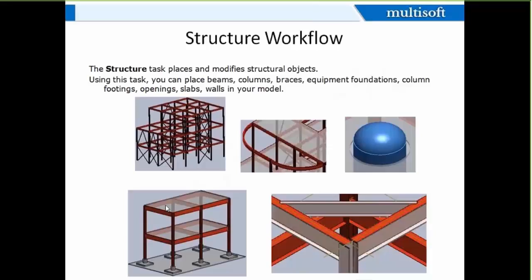You can see here there are different types of slabs available here. You can place the slabs or the checker plates or deck plates, anything. You can add the fireproofing also to the structure, like the insulation for the piping. In the same way, structure will have the fireproofing. You can add the fireproofing as per the requirement. And you can have the footings, combined footings, individual footings. There are different types of footings available in SP3D.